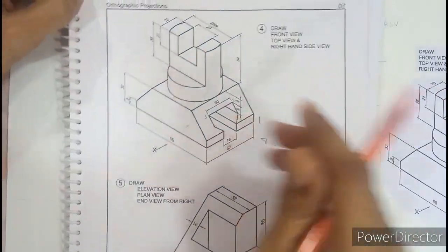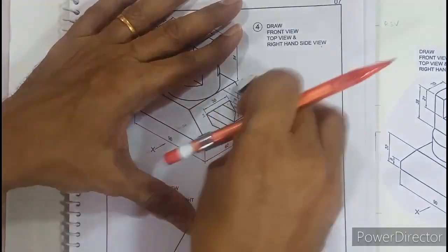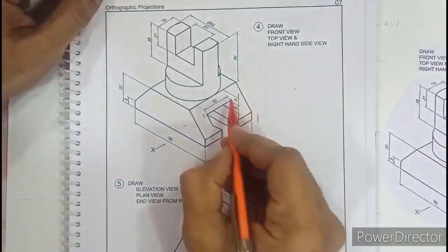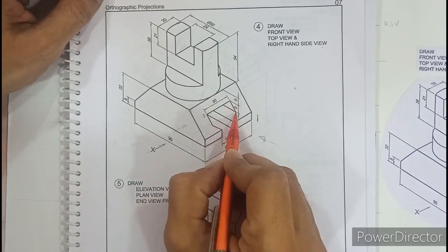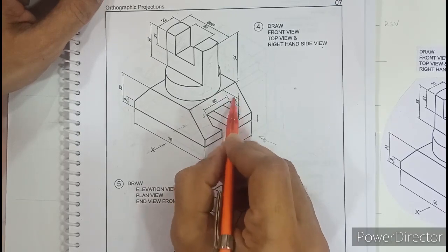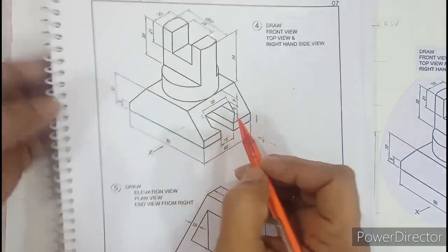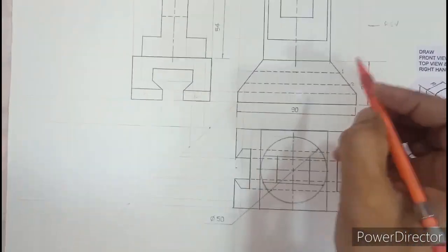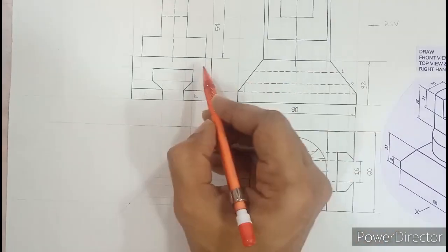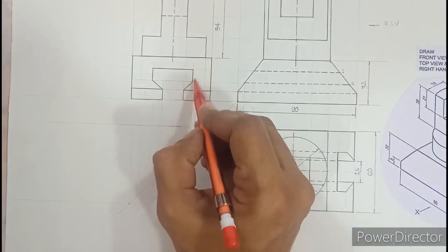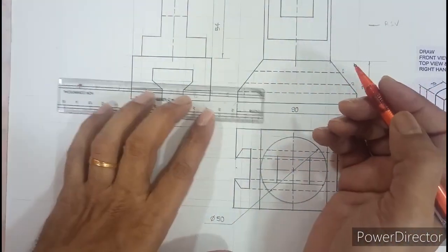Now let us see one new way of dimensioning. So if I erase this a bit. Yeah, this 9 millimeter is from the top of the platform. Then again 9 till the next edge. So I need to show this 9 and 9 together. As I told you, you should avoid showing dimensions from a hidden line. So it is advisable to show 9 mm in the side view. So how to show 9, all of you carefully look here.